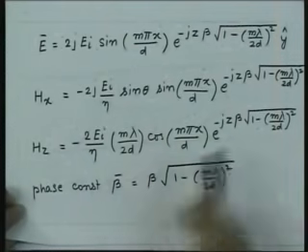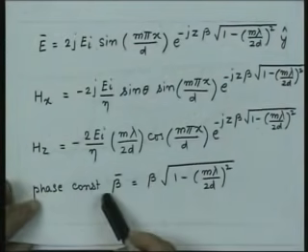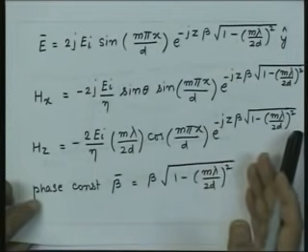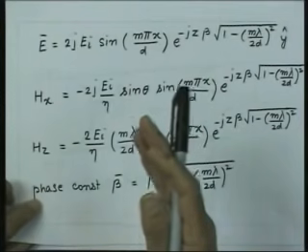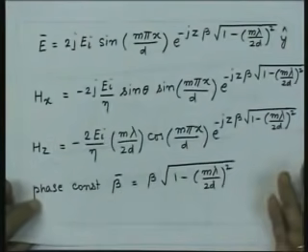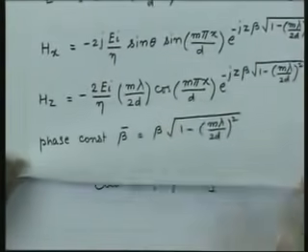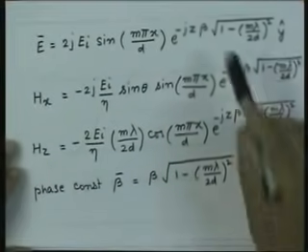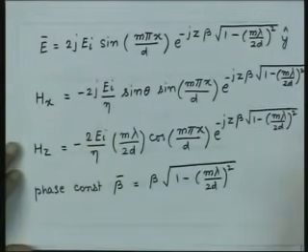So, beta becomes imaginary, that means it is no more a phase constant, but it becomes an attenuation constant, and the wave loses the wave nature. It represents only the field which is exponentially dying down, because we have only an attenuation constant and there is no phase constant. So, when you have a frequency below this cutoff frequency, it represents fields which are exponentially decaying, but there is no propagation of electromagnetic wave.